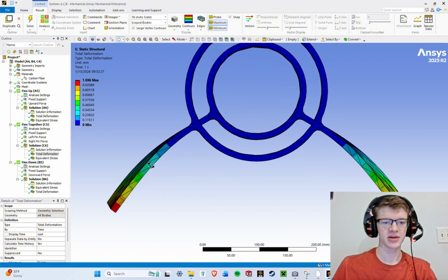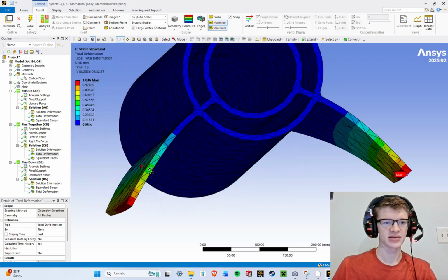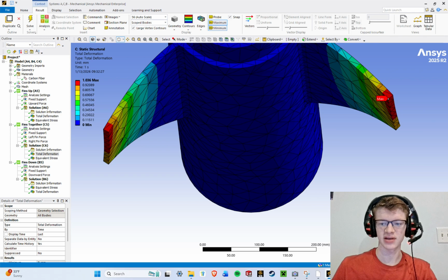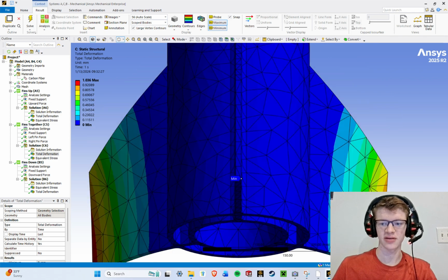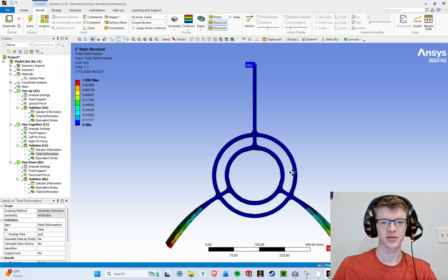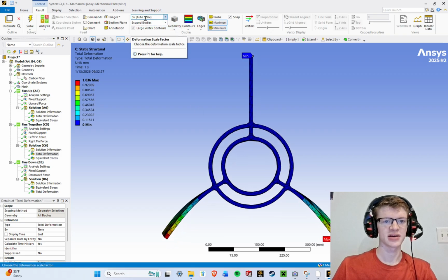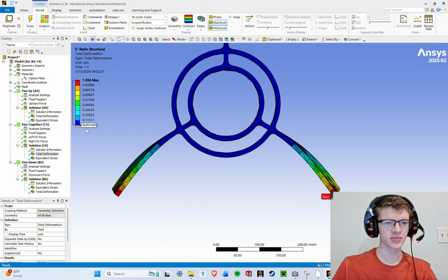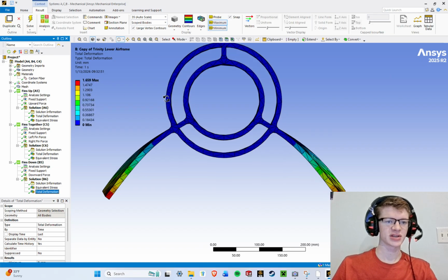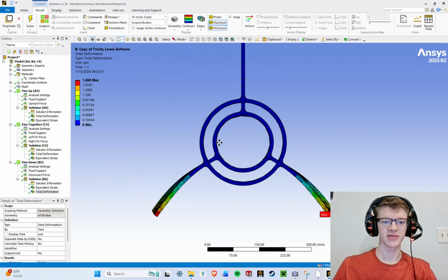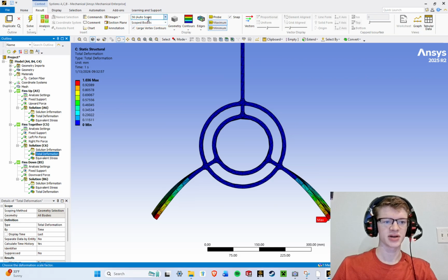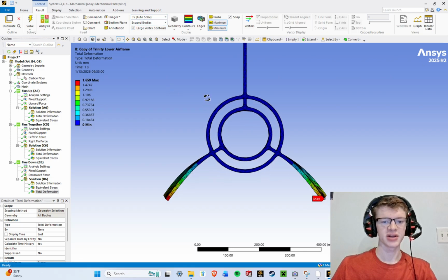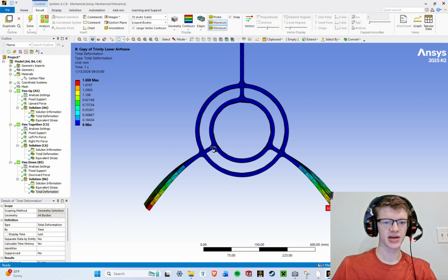Well, it's important to remember that the visuals in Ansys are not necessarily accurate because they are mostly for just gathering a general interpretation and not for precision, because things are scaled. If you look, the total deformation here at a maximum is 1.036, but here it's 1.659, so we should expect a variance in how much it bends. But the scale here is 56, well, the scale here is 35, and it's doing this to display it in a more user-friendly format, I suppose.